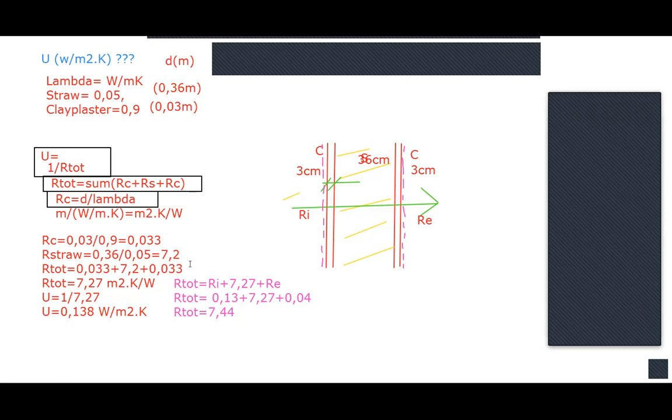This is the lambda value of straw bale, measured with a 20% safety addition, because it is a natural material, so it's 20% worse. This number, 0.052, is higher than what was measured. So there is already some safety factor. Some real measured values were even lower, like 0.04. So it's really good.